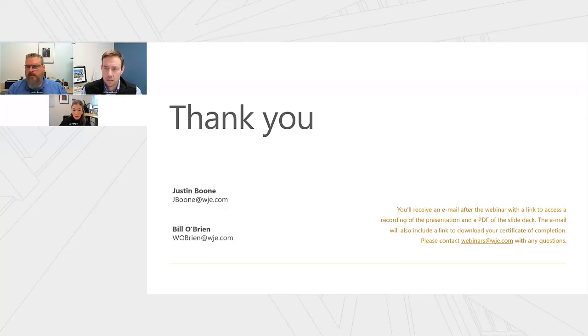Okay. Can you pressurize a building utilizing its own HVAC system? So yes, and for diagnostic testing, especially for larger buildings, if we can get the mechanical engineer and/or the building staff that know how to operate those systems to create, we like at least a 15 Pascal difference. I'd rather see it 20, 25, or even higher.